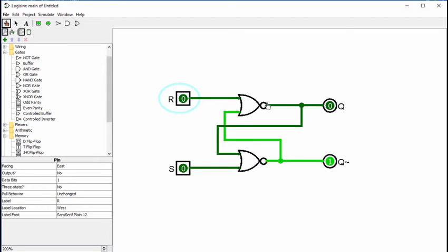The one thing where these stop being the opposite of each other is when, in this NOR gate world, we set them both as a 1. When they're both at a 1, both the outputs are zeros. This is not bad in and of itself. No circuitry is going to burn up. But the next question is,